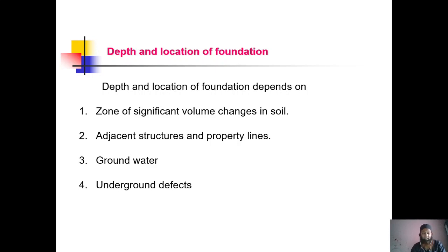Even this matters. Groundwater: if there is some groundwater, then you will have to move your footing from that side and relocate it at the other side where there are no groundwater problems. Sometimes there are some underground defects also, some reactive materials, which have to be checked before finalizing the footing. Even this has to be seen. If this is not seen and the footing is not placed at the proper location, then there are chances of settlement as well as base shear coming up there.